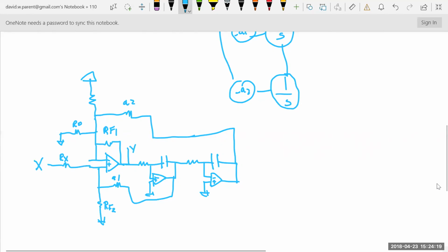Anyway, how to calculate these? I did a 5th order Butterworth low pass example. There's a video, there's notes when you're working on your project. I came up with what I think was a pretty straightforward way to make sure you get it right the first time. Now, would you label this A2 and label that A1? Well, I don't, because they could also be B1 and B2, right, Artem?